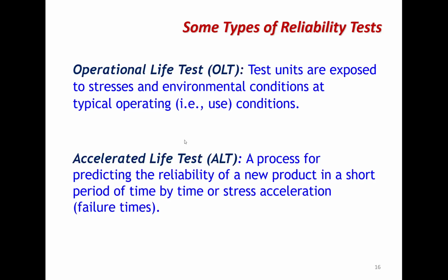So then people came up with, okay, what about this? If I expose the test units to more severe than normal conditions, for instance, higher temperature, higher relative humidity, a higher current, so that those devices can fail in a much shorter time. So this is the concept of accelerated life testing.